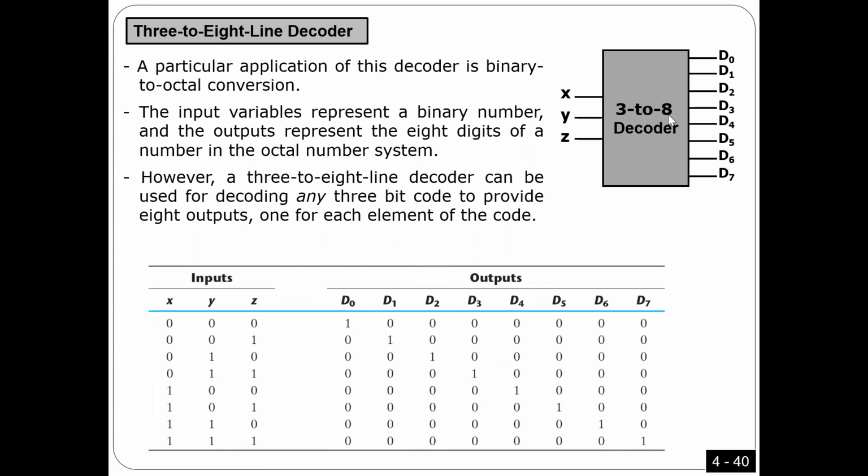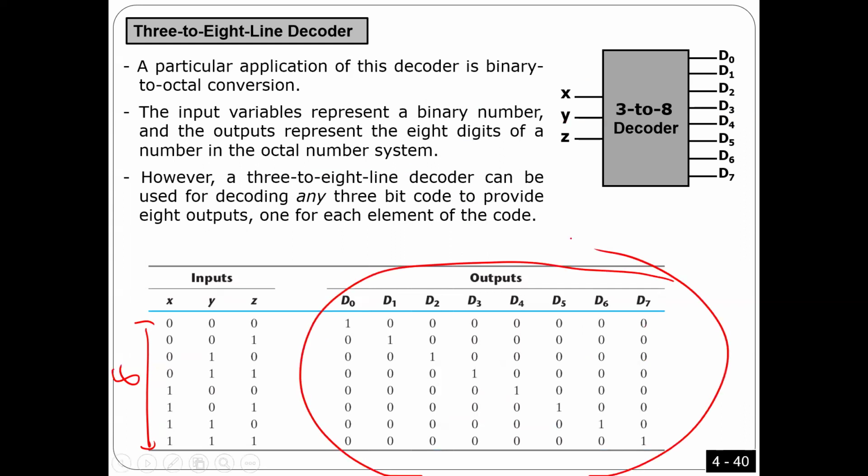Here it's exactly the same thing, but what I did here was a 3 to 8 decoder. Everything is the same, but in case you have 3 inputs, I'm going to have 8 cases. Based on the number, for example, if the input is number 5, I will find D5 here is 1 and everyone else is zeros. Okay, guys, any questions?